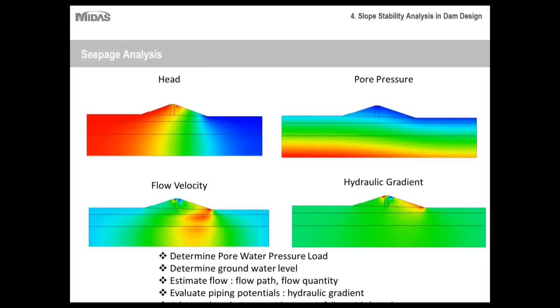That way, engineers can determine whether or not the seepage, or the forces that are acting upon the slope due to seepage, would warrant maybe a redesign or any type of structural support.